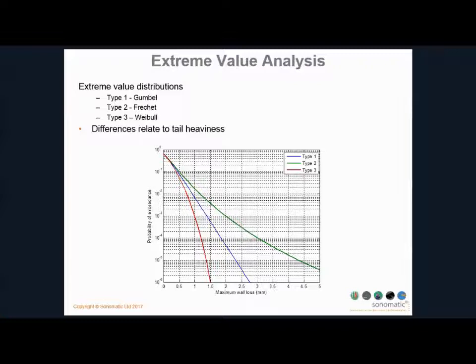So typically for statistical applications, if you get any indication of a heavy tail distribution like this, either within the extreme value or in the underlying distribution, that's a situation where you wouldn't be comfortable applying statistical analysis because it becomes very difficult to quantify the reliability. You've always got a likelihood of having quite significant corrosion, or much more significant corrosion, in the area that you haven't inspected.